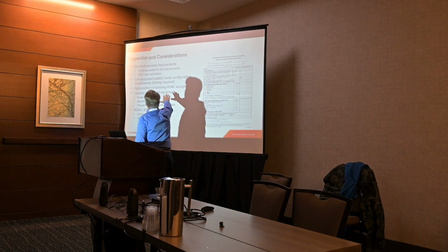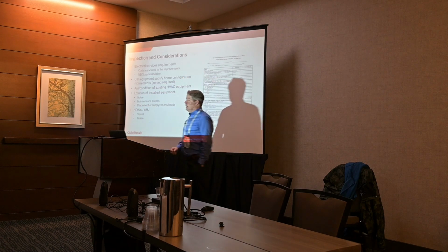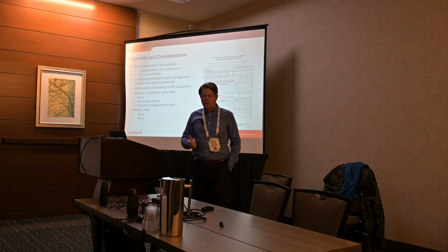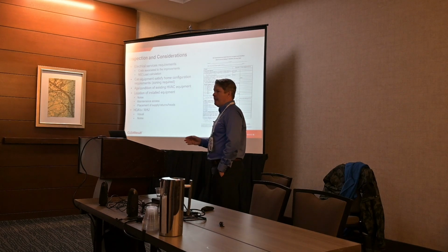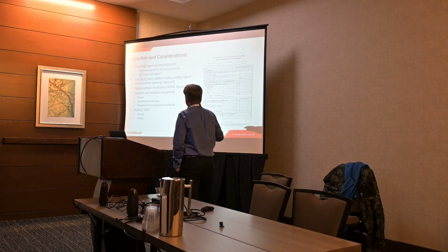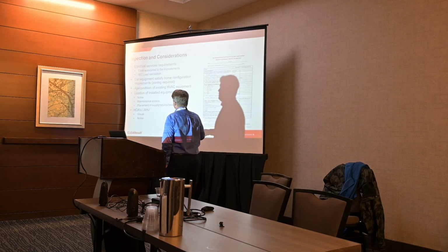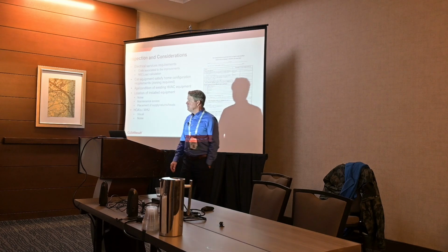Okay, so location of the installed equipment is kind of important also. The outdoor units are more quiet than they used to be, especially the mini split ones, right? But they're not dead quiet, right? You can still hear them. They kind of have that whine too. So if they're too close to where the people want to be, then obviously it kind of ruins their outdoor space. We also need access for maintenance, right?